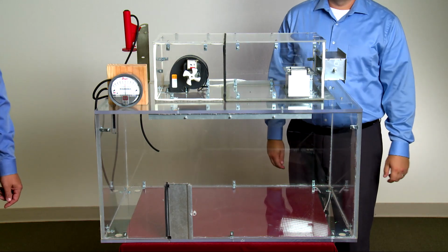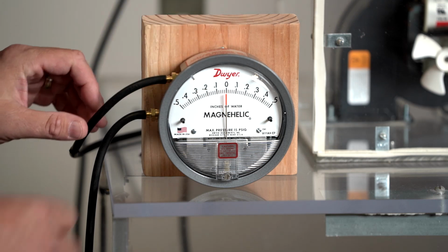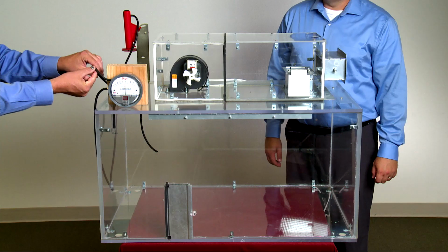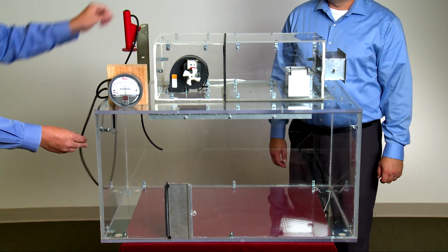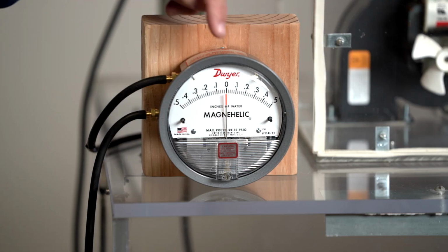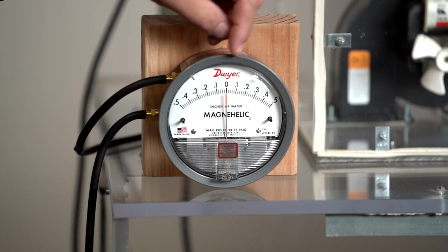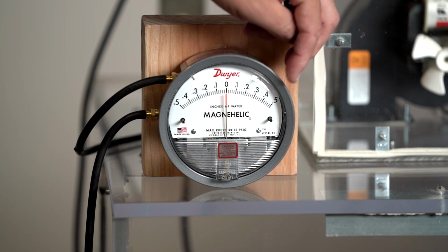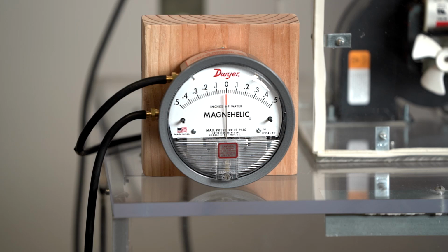Now we use this differential pressure gauge so you can visualize how the pressure changes. This is a Dwyer Magnehelic and it has 2 ports on the side. The tube attached to the high side port is routed down through the hole in our building. The tube attached to the low side port is connected to this red probe located outside the building. I'll talk more about this red device later. So this gauge measures the difference between the static pressure inside our model building and the pressure outside. The orange needle indicates the current measurement, and the gauge ranges from a positive 0.5 inches of water to the right side down to a negative 0.5 inch to the left.